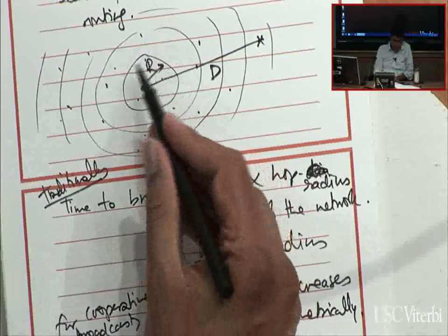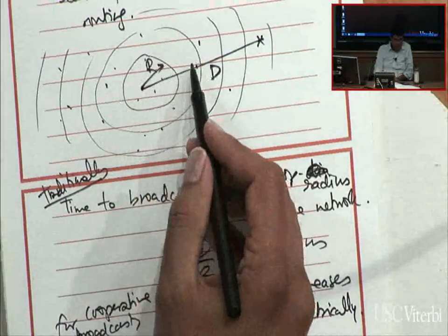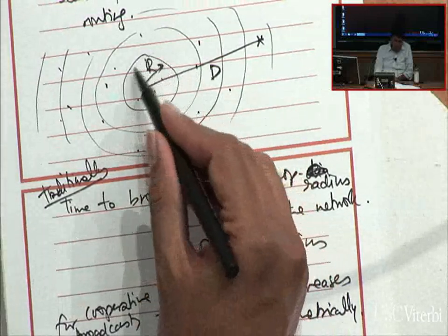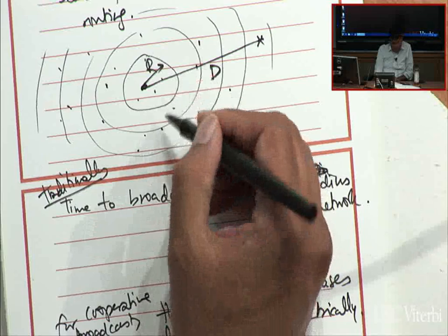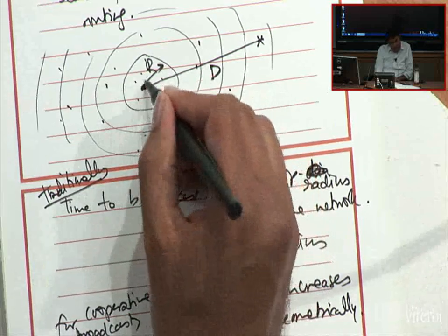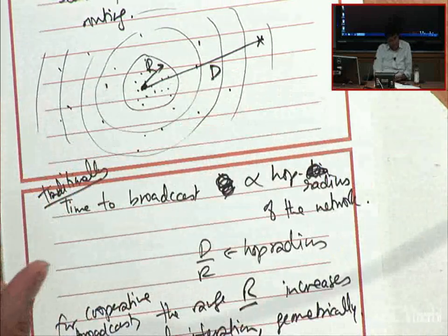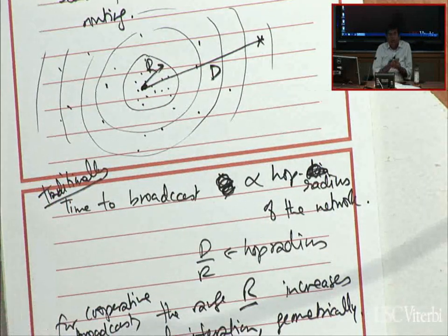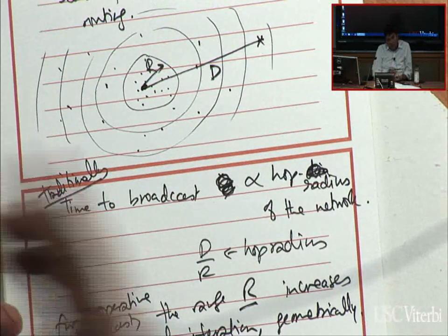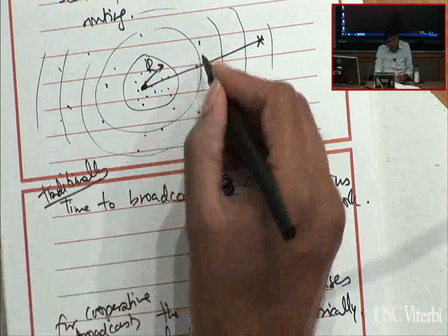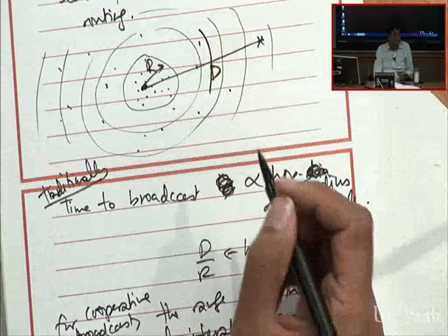So in the first round, I capture a bunch of nodes and they transmit. Now, the first node, when it was transmitting by itself, had a certain range. But after that first round of transmission, it's joined by a bunch of other nodes who have all received the packet after round 1. Now, when they all transmit together, it's not going to just propagate to this distance, but because they're cooperative, it's going to go a little bit further beyond.